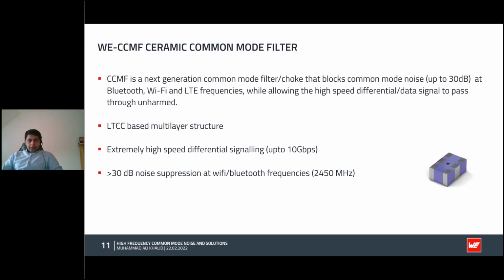Here I will talk about our innovative common mode choke, which is WECCMF, the ceramic common mode filter. It is basically a sensitivity improvement solution for your wireless devices at 2.4 gigahertz. This means that potentially the common mode choke or filter can be used in any wireless communication device which also has a high-speed digital switching interface. Common examples include smartphones or tablets, notebooks, routers, IoT-enabled devices, etc.